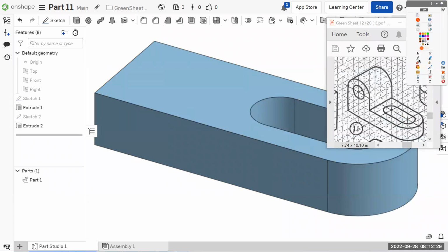And the second portion, it is a footprint of 4 by 4, so it travels the entire distance front to back and 4 wide. Then we could, why don't we do a 4 by 4 by 4 brick sort of block cube thing. Then we can fillet over these 2 edges in a single move, and then make this circle, which will be super easy in a single move.